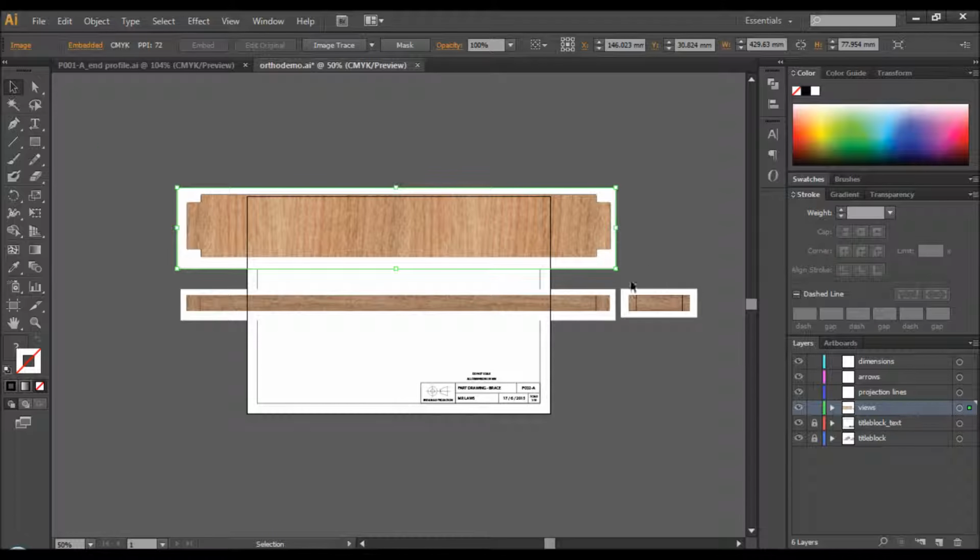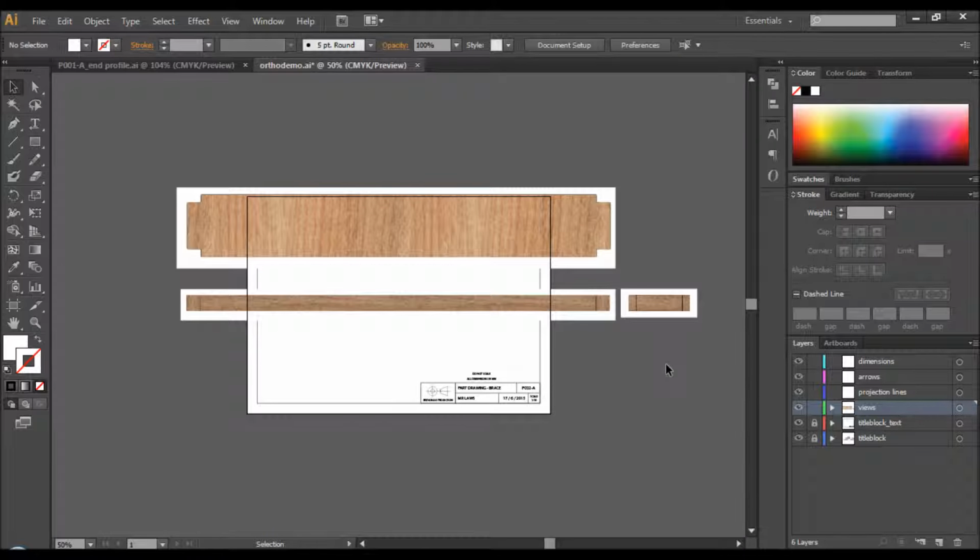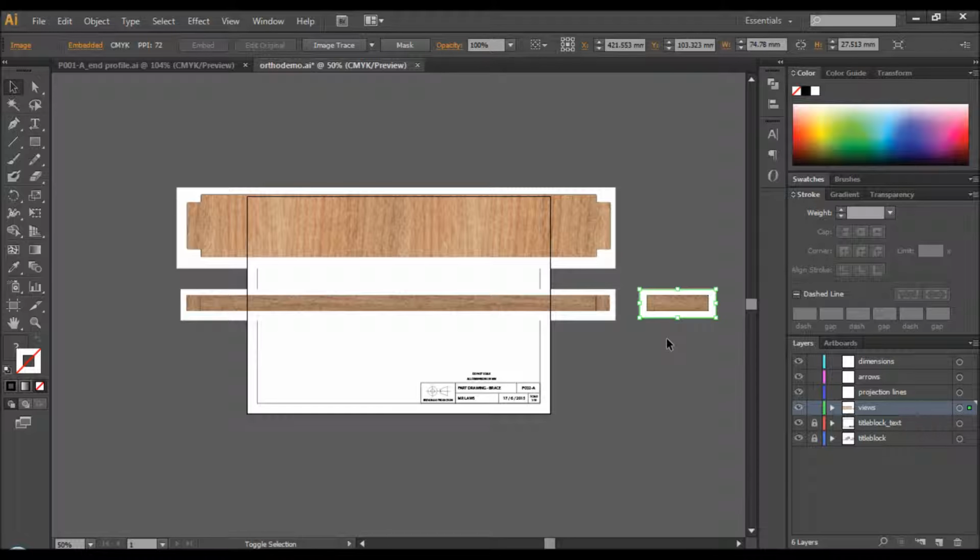Okay, in third angle projection, the top view should be on top, the side view should be to the side, and it's really quite logical in terms of that. So just remember that when you're laying out. Everything should line up perfectly, and the relationship between each of the views is very important.